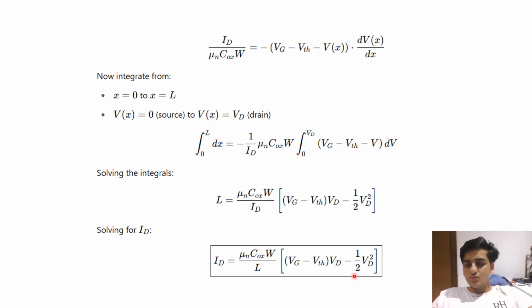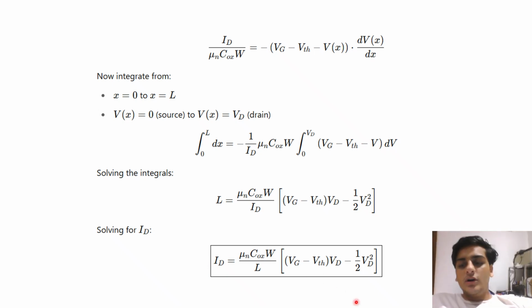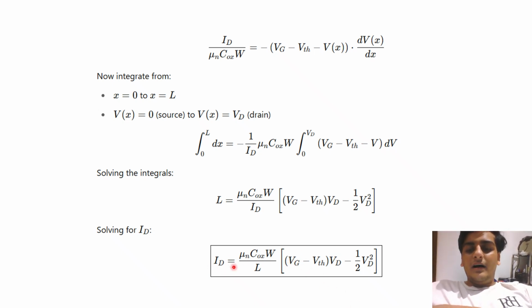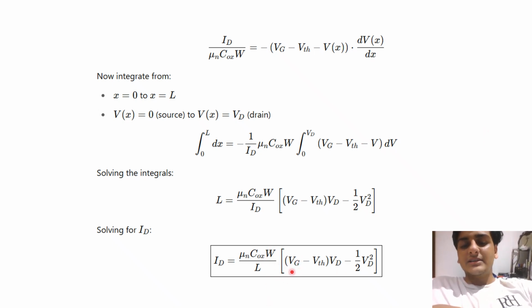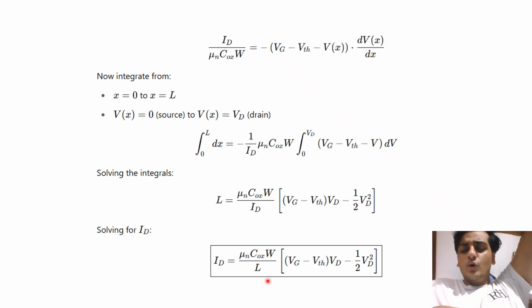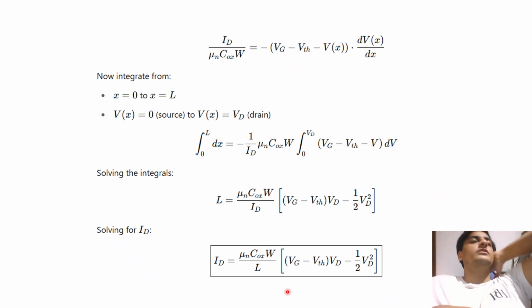You can just think of it as voltage and current. The technical terms are drain voltage and drain current. So for each gate voltage, you have a specific curve. We'll see how those curves look in a second. You have a family of curves with respect to the value of gate voltage, and obviously if your gate voltage is higher, that curve is going to be above the lower gate voltage curve.